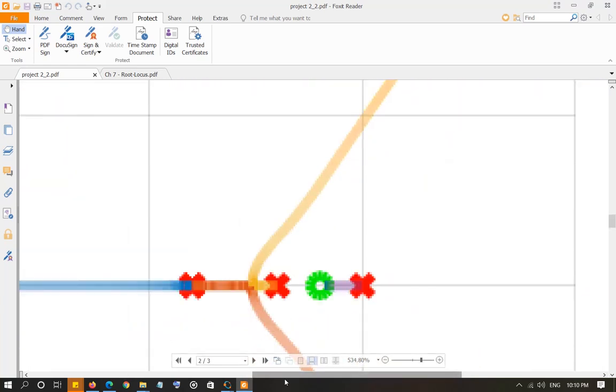Okay, so now when you have a set of root locus on the x-axis, and if you keep increasing the value, and if it breaks away from the x-axis and goes into the x and y domain, that is, the system is becoming a critically damped system because it will have complex conjugate roots. This point where the system leaves the x-axis and then starts moving in the xy plane is called the breakaway point. So that's the breakaway point.